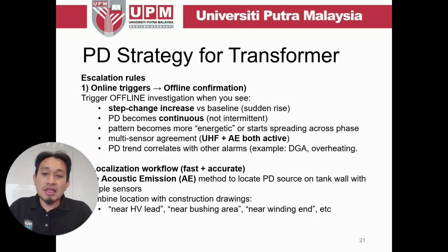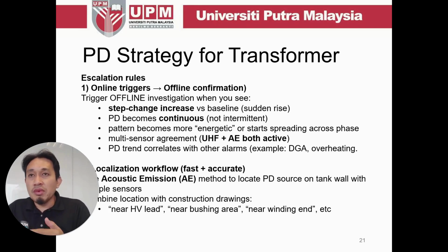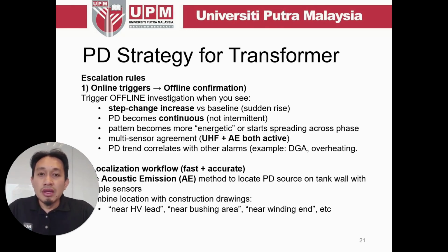Another strategy is to use acoustic emission to localize the PD and understand the source of the PD, as well as confirm it with the construction drawings, whether it's near the HV lead, near the bushing area, or even near the winding itself.